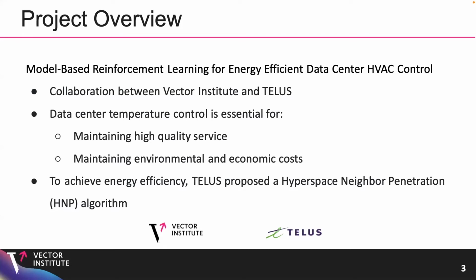For instance, a cooling strategy that uses unnecessary or excessive air conditioning will consume more energy than a strategy that better leverages free cooling. Free cooling is the process of cooling by exchanging heat with the lower temperature outdoor air, making it a more cost and energy efficient cooling approach. As long as operational constraints are satisfied, opportunities to discover temperature control solutions that minimize energy consumption are highly valuable.